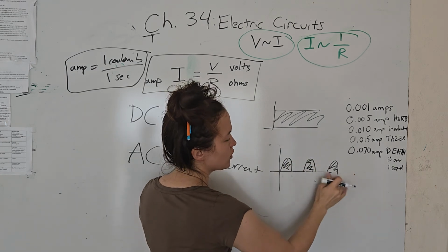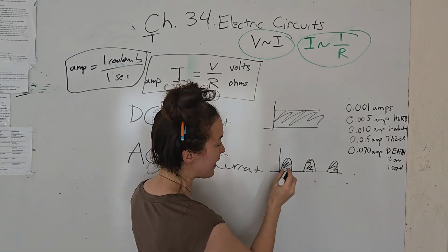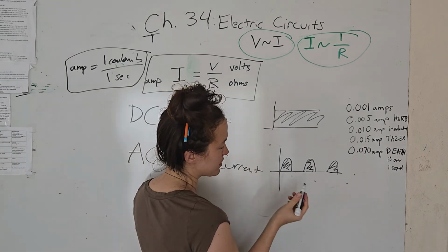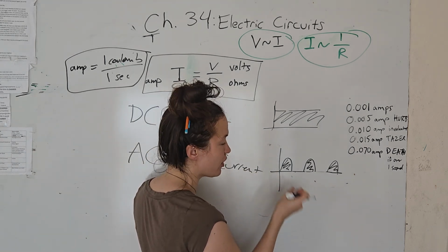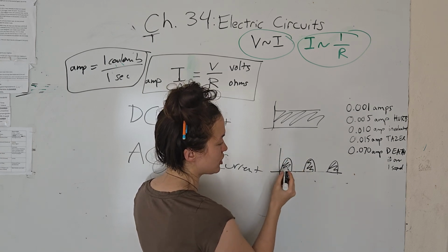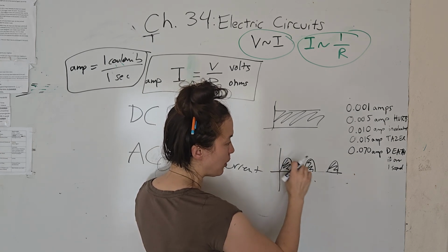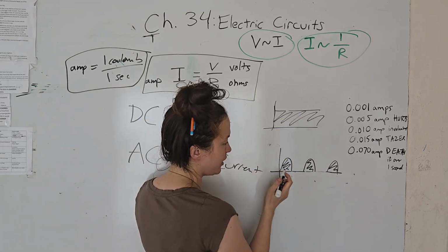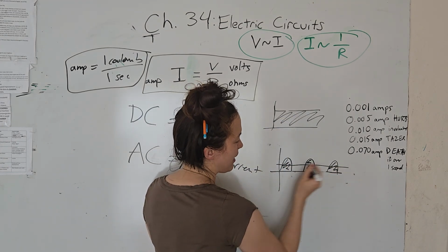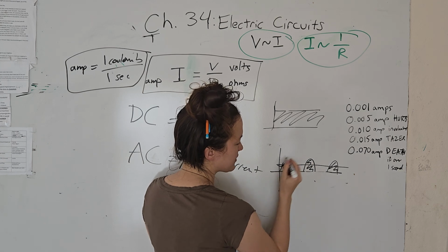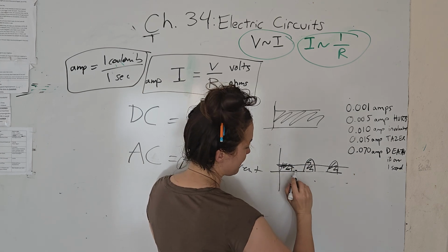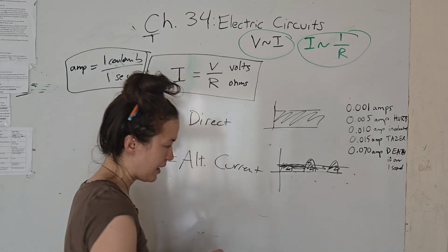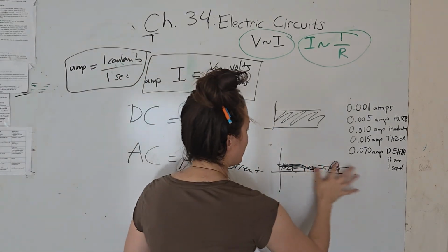moving in one direction. So it looks kind of like this, and then they will have another diode that reverses polarity, or sometimes they'll have capacitors that are getting charged up and constantly discharging. See, here I just turned the alternating current into a pulsing direct current. Instead, because of those capacitors charging up and discharging, it'll sort of average it out and look more like this.